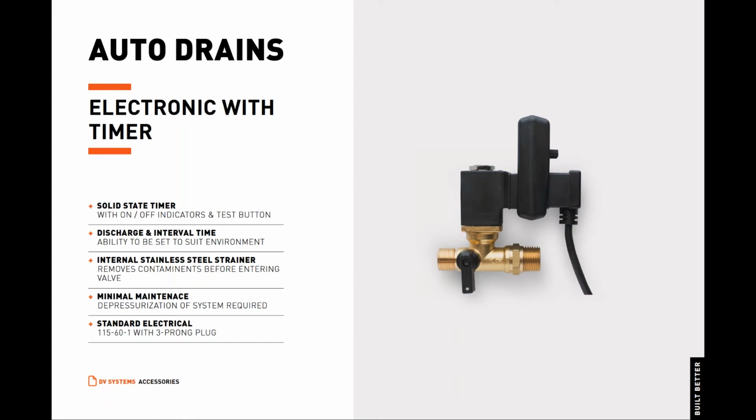The electronic auto drain with timer requires minimal maintenance. The stainless steel internal strainer should be kept clean. Maintenance and service work must be performed while the auto drain is disconnected from power and depressurized.